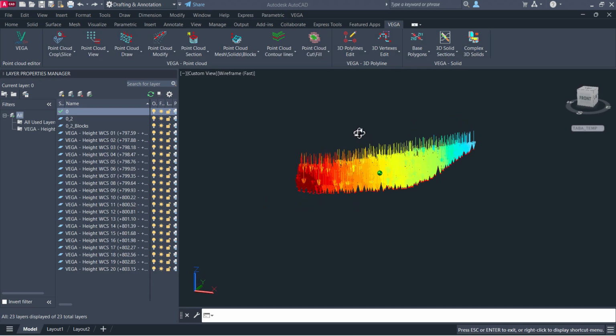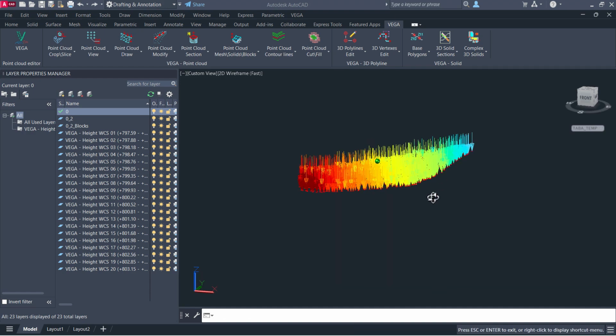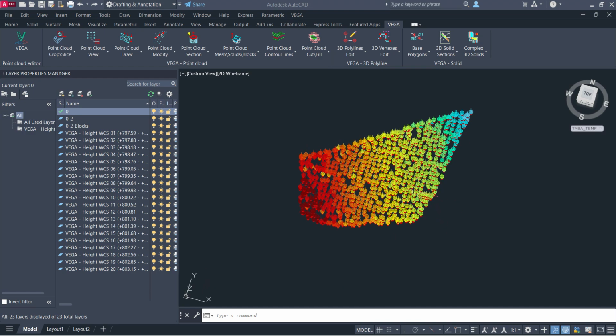Of course, it will be more difficult to mow the grass, as we did last time. We'll hide the point cloud and separate the key points by height. And if we look from the side, we will immediately see some points that are definitely in unnecessary places. In this case, to remove these objects, we will turn off the layers one by one so that we can find the unnecessary points. From the bottom to the top, I remove the points that are artifacts. In this way, we would gradually make a precise cleaning of the surface.